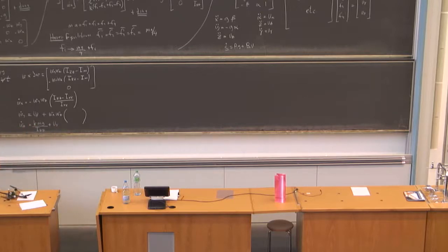And I'm going to stop there and just point something out to you. Well, I'm looking for an equilibrium here, right? So I want to look for an equilibrium where omega x dot is equal to 0. Well, that's okay because I have an omega y here. So if omega x and omega y are equal to 0, then omega x dot and omega y dot will be equal to 0. So I have an equilibrium here. This is my control input, right? But if I look at this, I just notice that there's a constant term here plus my control input, which is assumed to be small, right? I'm controlling it about this equilibrium. This could be large. That means that there's no way for me to have an equilibrium for omega sub z.